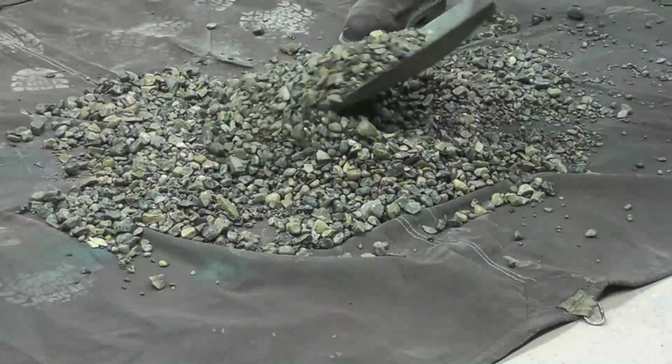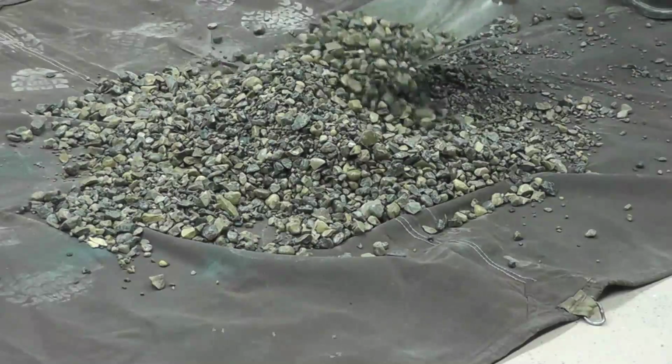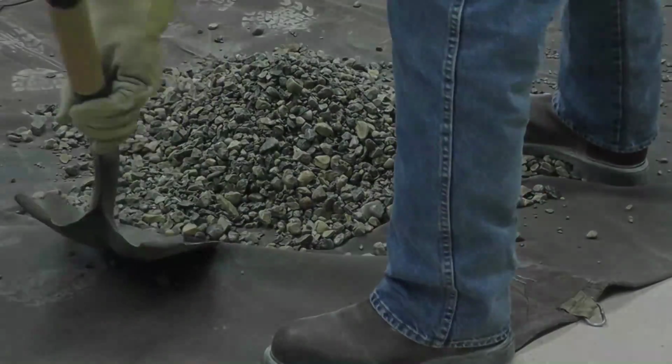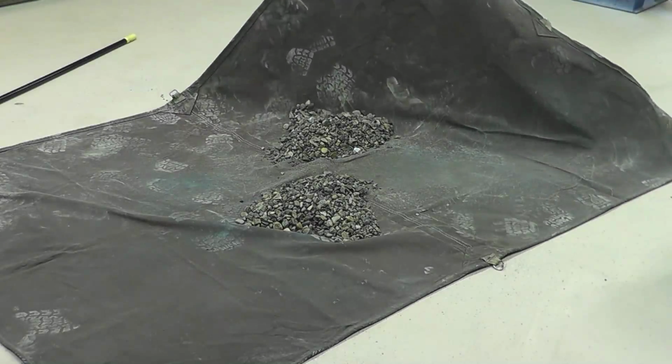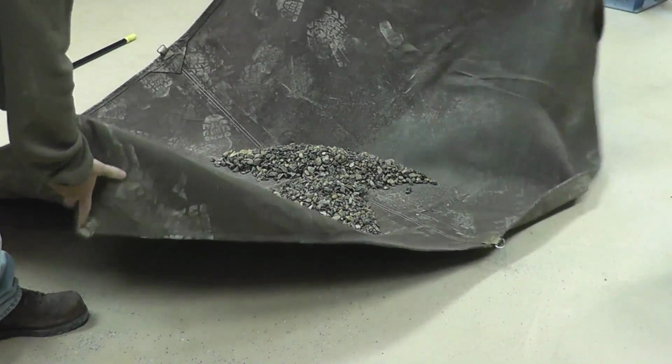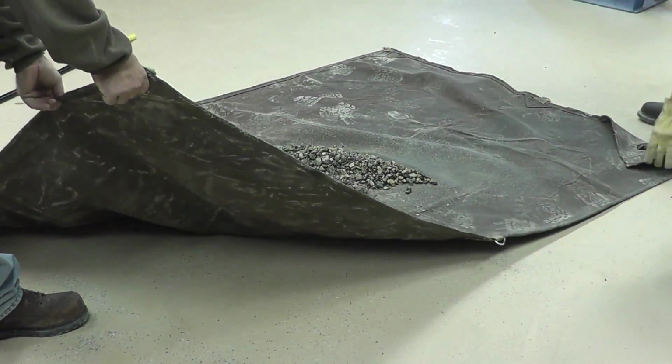As an alternative to method B, when the floor surface is uneven, the field sample may be placed on a canvas blanket and mixed with the shovel, or by alternatively lifting each corner of the blanket and pulling the blanket over the sample toward the diagonally opposite corner, causing the material to be rolled.